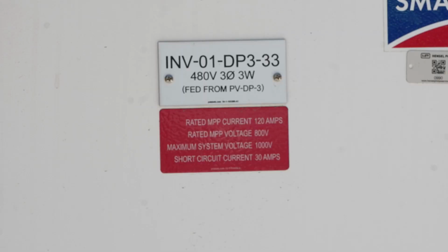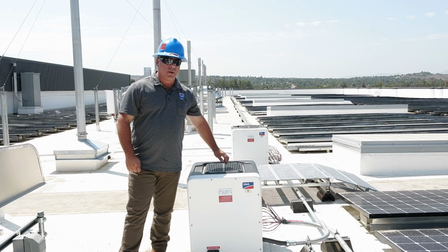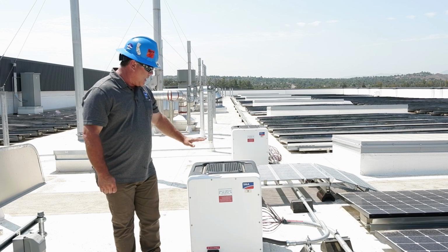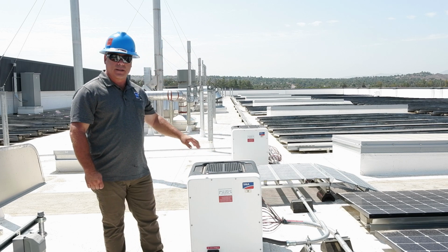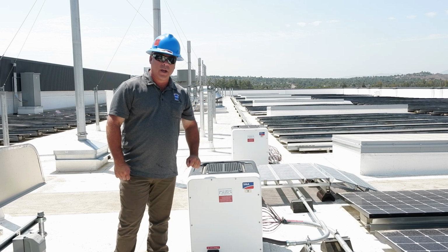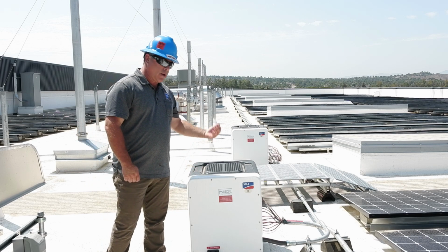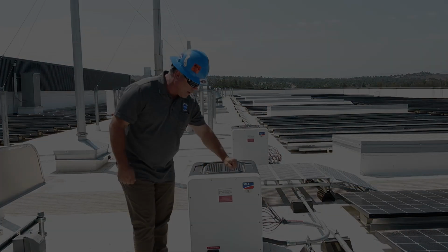This one, the max it'll do is 33 kilowatts. The 50 will do 50 kilowatts. 62 will do 62 kilowatts. It's an SMA inverter. And we can see on the top that we have a grill. For maintenance, it has to be clear of any debris or leaves, dust, dirt. If we can keep it clean, it'll help the inverter stay cool. The air flows from the bottom and it goes by convection all the way up. There's fans working, so we want to keep this clear.